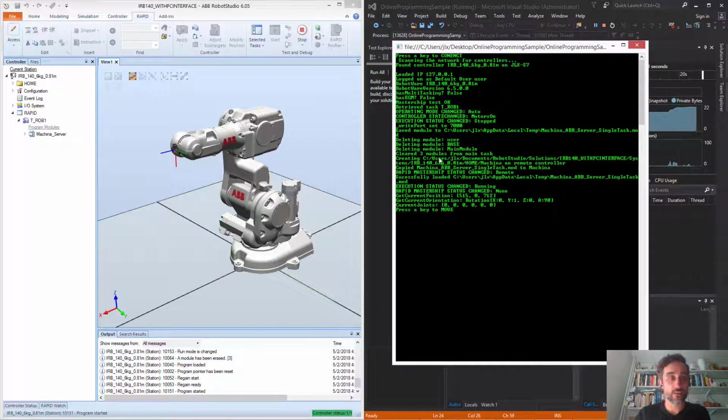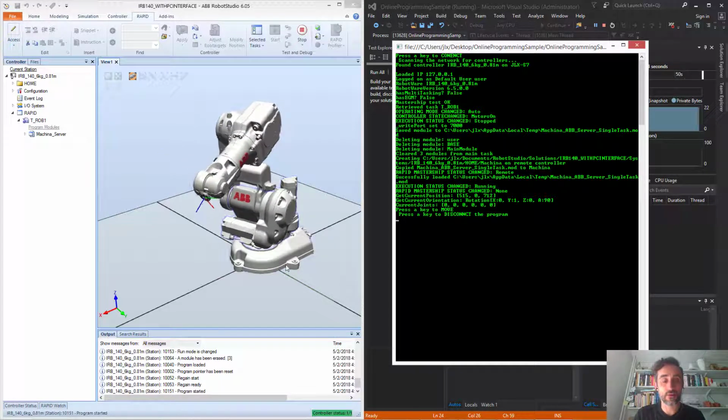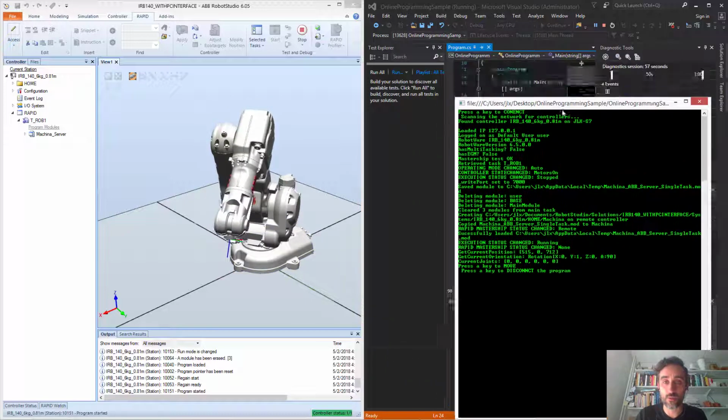and you can see that right now the program changed to this thing called a Machina server, which is a module that gets uploaded to the controller so that communication is live, and that the program right now is actually running. So you can see that I have the stop option because this program is running and is listening to actions that are going to be streamed by Machina. So Machina is prompting me to press any key to move, and as soon as I do, Machina is going to start streaming actions to the robot. So those actions that we wrote in the program.